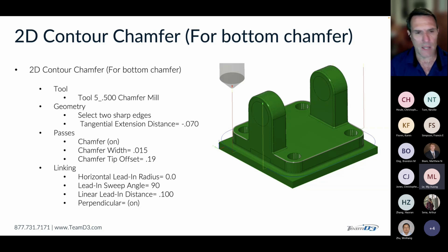The other advantage of using cloud-based libraries is that if the speeds and feeds need to be adjusted, maybe it turns out someone did some experimentation, and with aluminum, a different spindle speed seems to work a little better with a particular tool. You can update that, and next time someone goes to use that tool, it will have the latest and best information.